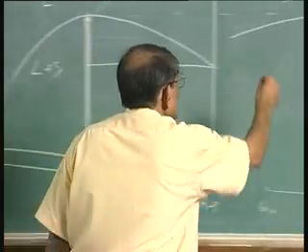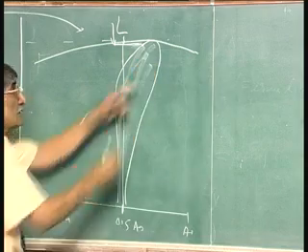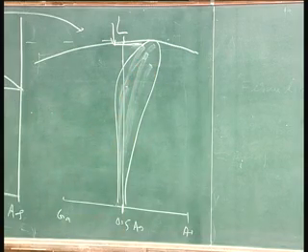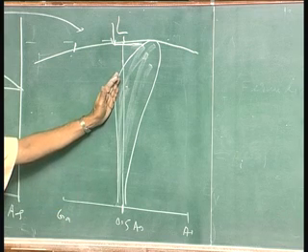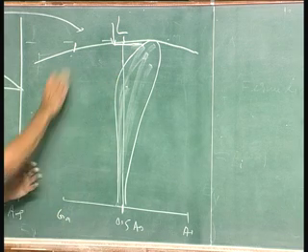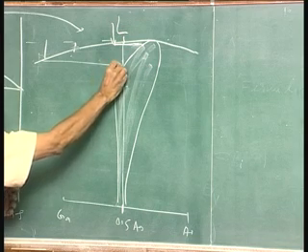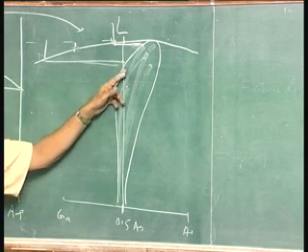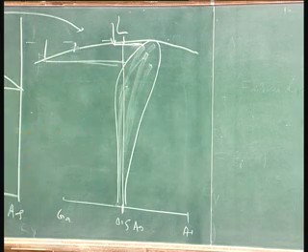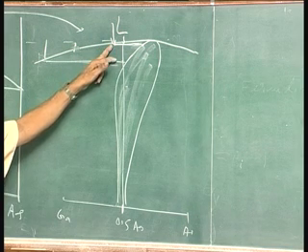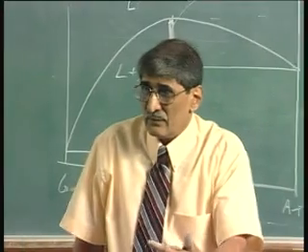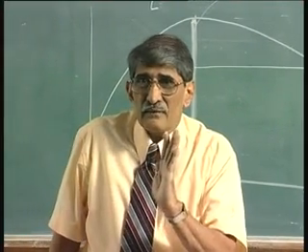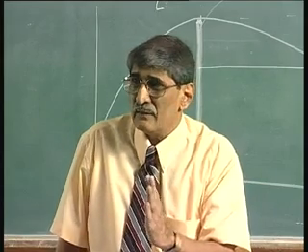If I go on to this side, all the time you will get this, but if I go on to that side, you may not have these anti-site defects, because if I come down from here, it may come here, just about stoichiometric. The melt is actually not non-stoichiometric, but the composition that you get is arsenic rich. That is what you are looking for. So that is why you get high resistivity material when it is more than 0.475 arsenic.